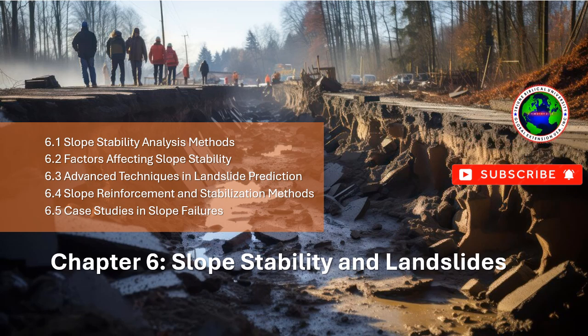6.4.5 Rock bolting. Rock bolting is a technique commonly used in mountainous or rocky terrain to stabilize slopes and prevent rockfalls. It involves installing steel bolts or anchors into rock formations to increase the strength of the rock and hold it together.